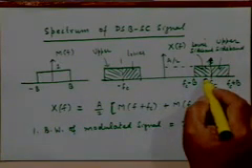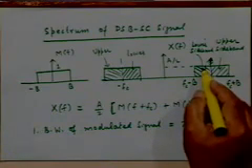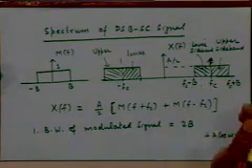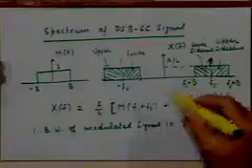Of course, if the signal spectrum is non-zero at 0, it will imply a non-zero value of the spectrum here. That is true, but this is a spectral density. It doesn't mean that there is a carrier component. For a carrier component to be present, you must have an impulse function there. Suppose I ask you what is the energy present in the signal at any specific frequency? It is 0, because this is an energy density function, an amplitude density function. So the actual amplitude will be proportional to the area under that curve. The area occupied by a single point would be 0, unless there is an impulse present there. Since there is no impulse anywhere here, and specifically not at the carrier, we call it double sideband with suppressed carrier.